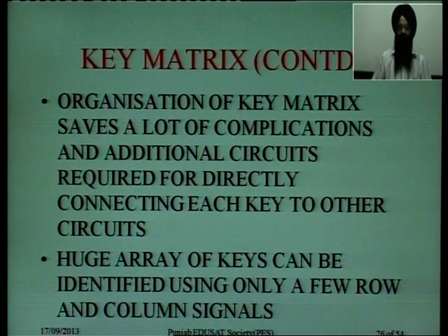The organization of key matrix saves a lot of complications and additional circuits required for directly connecting each key to other circuits. The huge array of keys can be identified using only a few row and column signals.